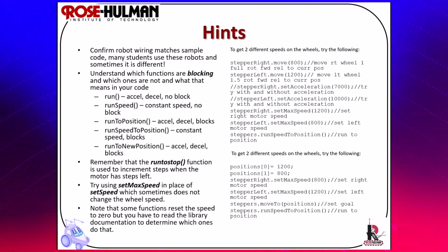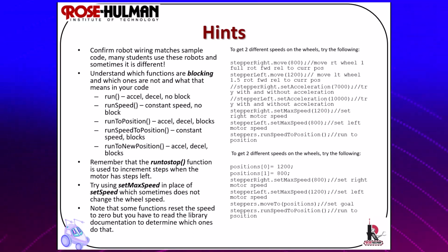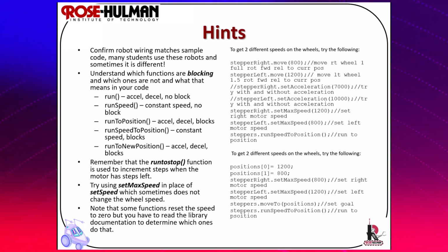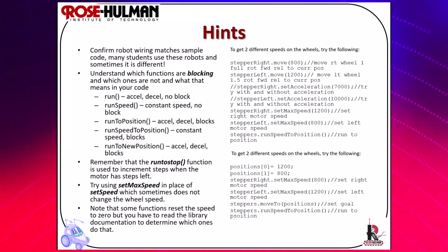Most importantly, if you are running a function that is blocking until it finishes all the steps or all the movements or gets to that final position, it hangs up the code and nothing else will run. Also remember that the run function is used to increment steps when the motor has steps left, so it will continue to run until it has moved all of the steps. Also setMaxSpeed and setSpeed. Some functions in the library reset the speed to 0. Depending upon the function, either setSpeed or setMaxSpeed will be required in order to vary the motor speed.